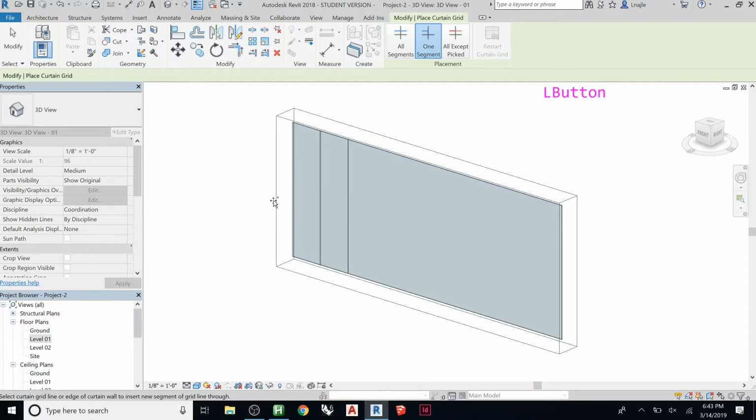And this even has some standard snap points, like 1/3 of the panel, or 2/3 of the panel, or the center point of the panel. So you can go in here and start breaking this up either by clean dimension or something else. So let's just say every 4 feet we wanted to do that. That's pretty good. 4, 4, 4. And let's say here you wanted to stagger it, so not 4, but we could do 2, 2, 2. So then it's the same kind of module, but here it's broken up.